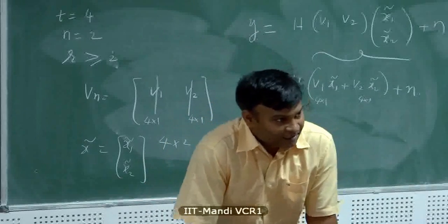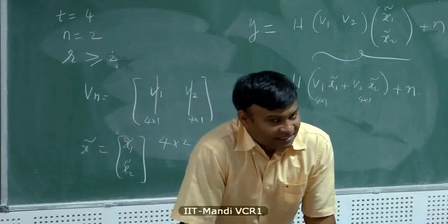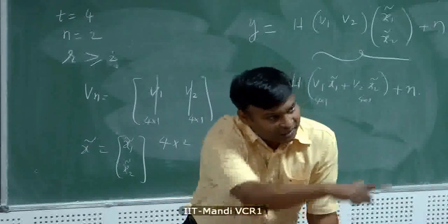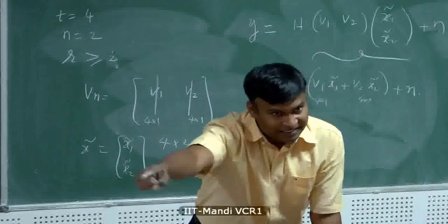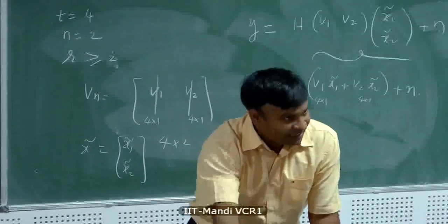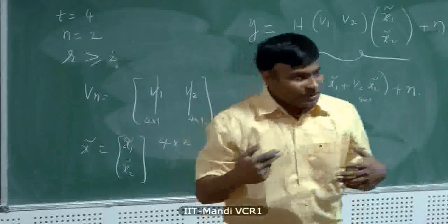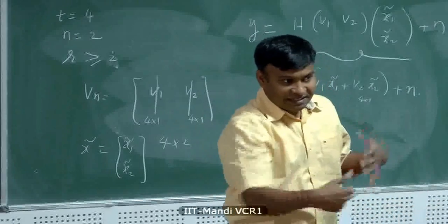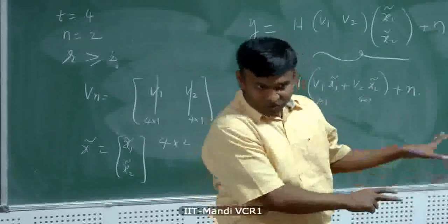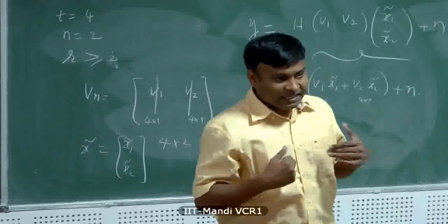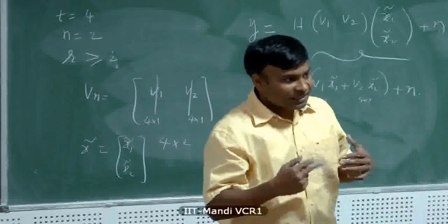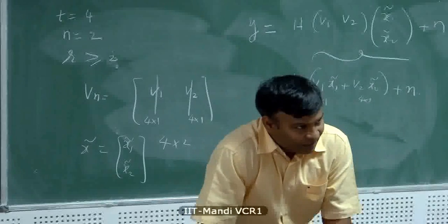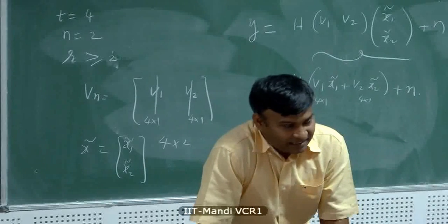Why is that? Is that an anomaly? Well, it's not really an anomaly. First of all, you get a diversity gain. As the number of receive antennas increases, you get receive array gain, and your diversity gain will be a product of the number of transmit and receive antennas, which you can show. If you have a single stream, and T transmit antennas and R receive antennas, T multiplied by R is the diversity advantage. But array gain is lost.